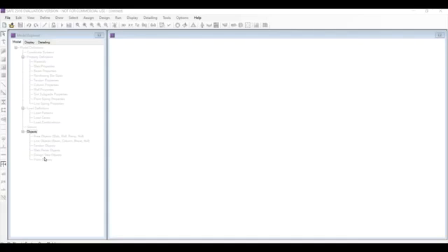We need to have all these base reaction values so that we can assign those load values to the mat footing. Before designing a mat footing, we will assume our own data and do the design. So let us assume a mat footing of 18 by 18 meters dimensions, and we will be having 4 by 4, that means 16 columns in the mat footing. And let us give our assumed column dimensions.